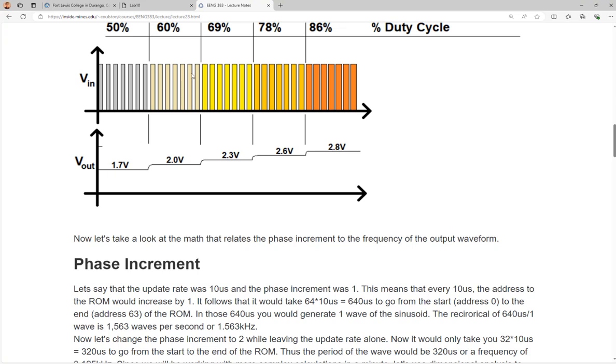So if you keep changing that PWM over time, eventually you are generating this kind of waveform very similar to a sine wave. So it could be a sine wave, could be whatever signal you have, depending on the bytes you have in the SD card. That's why when I'm reading from my SD card, I'm playing my song, my recording. Even though it's not a sine wave, because an AC signal can be anything. They are just bytes. Okay?